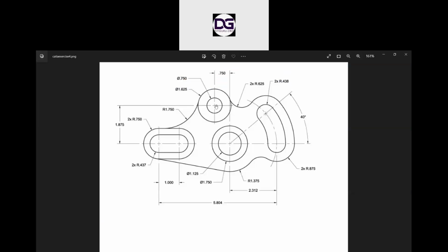That is, you can make this circle, give the dimensions related to it, then make another circle and give dimensions related to it. You can approach either of the ways as you like. So I will make the geometry and constrain it, give the dimensions, then go to the next geometry, constrain it and move forward.